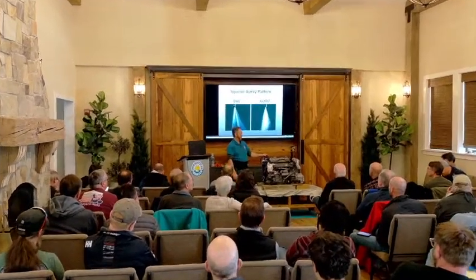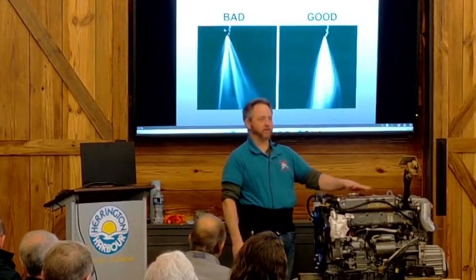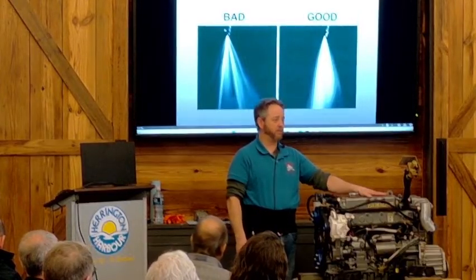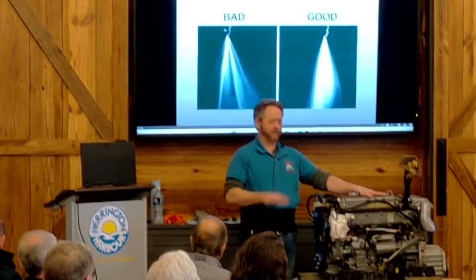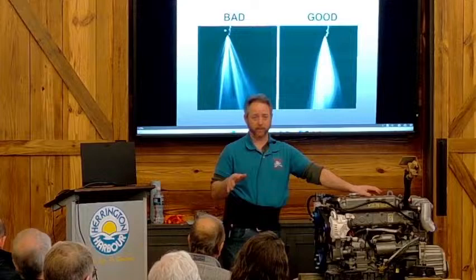Yeah, so the coolant that's in the engine, almost all of us are going to be using a 50-50 mixture of coolant and distilled water. The only people that would be different would be the people with the Volvos. I think they use a 60-40 mix.